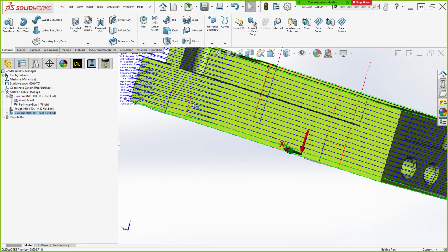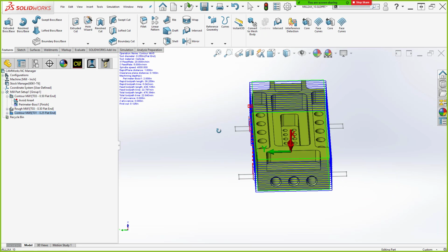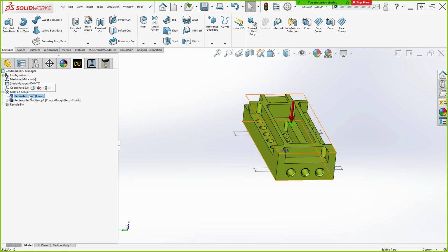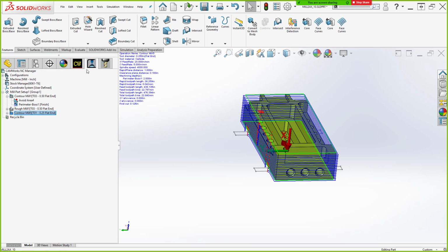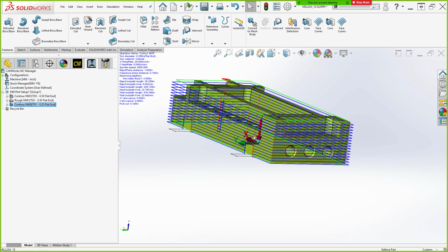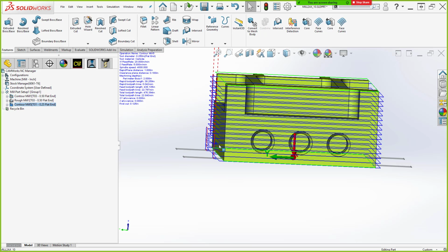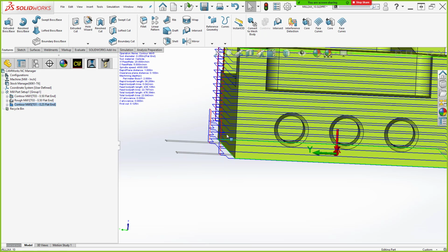And now I'm doing avoids on this side. So Derek, I hope that answered your question. It's a pretty quick and rough answer, but don't be afraid to duplicate steps or duplicate setups. We're doubling up on this a little bit, and there's a lot of extra toolpath going on in here, like we're cutting the Z heights way too much. We only really need this to happen for the last little bit where the clamps are.